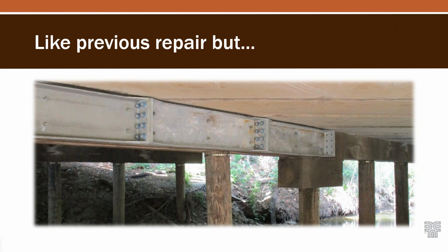But right now, how it's shown, I have the load coming from the slabs into the channels, but the channels aren't making a direct connection to the pile. So I haven't actually replaced the original timber cap. I've just kind of helped reinforce it.